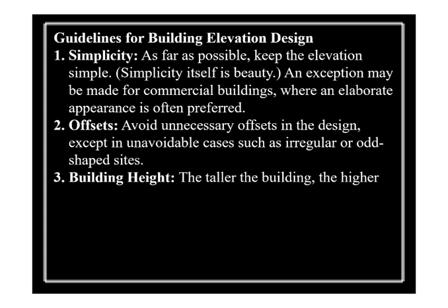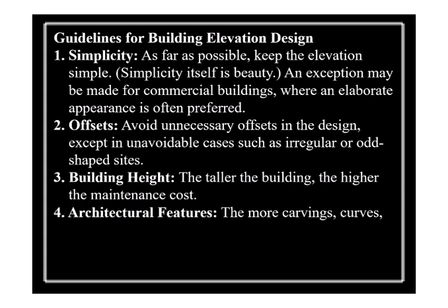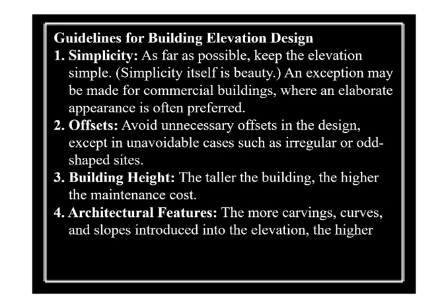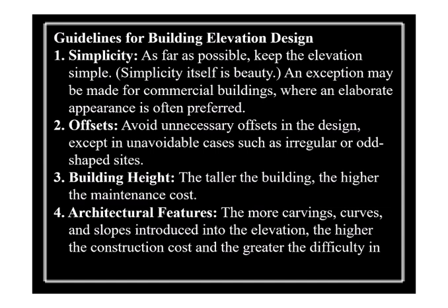Building height. The taller the building, the higher the maintenance cost. Architectural features. The more carvings, curves and slopes introduced into the elevation, the higher the construction cost and the greater the difficulty in execution and maintenance.